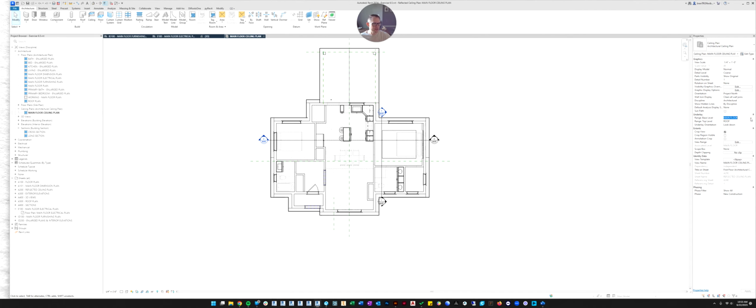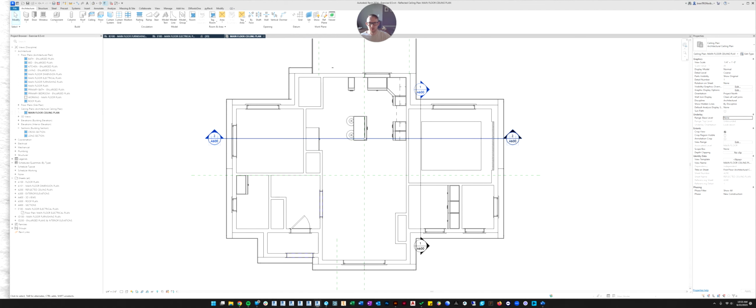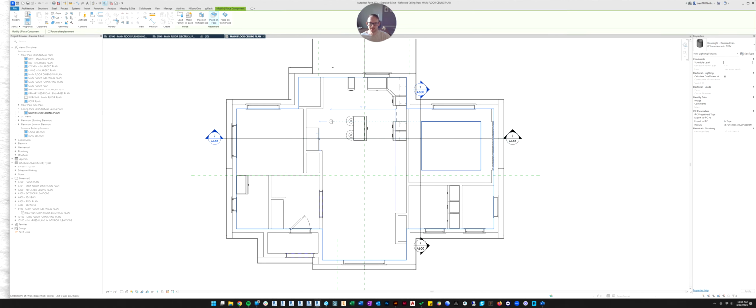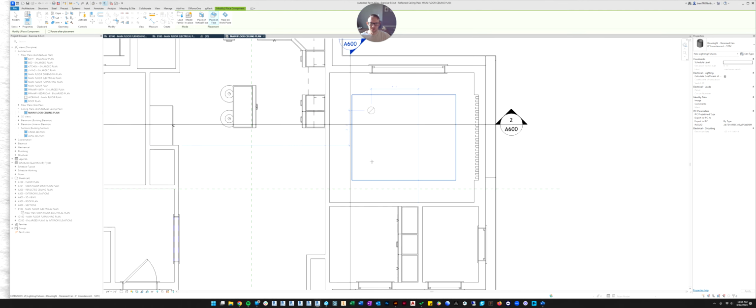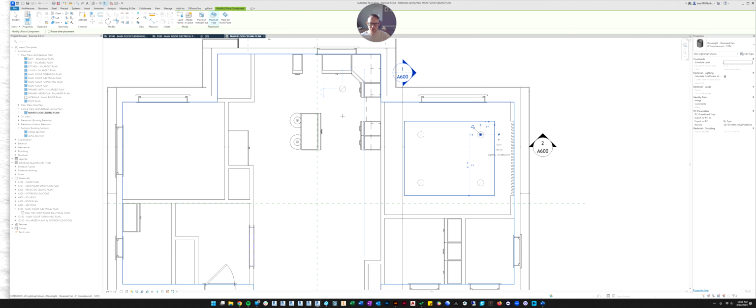So I'm going to shut the underlay off to be none. So now I know I'm only looking at my ceiling, and we'll go back to place component. And now you can see it highlights the whole ceiling. That's how I know I'm placing it on the ceiling. So let's put the can lights back into this room. We'll put them back in our kitchen.